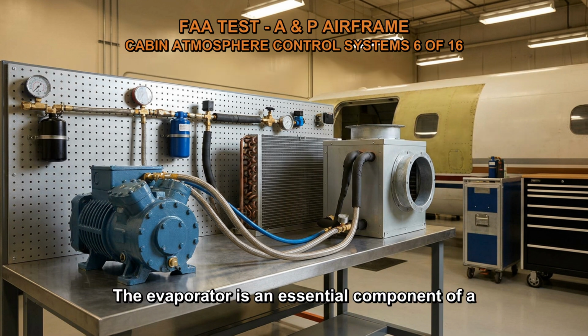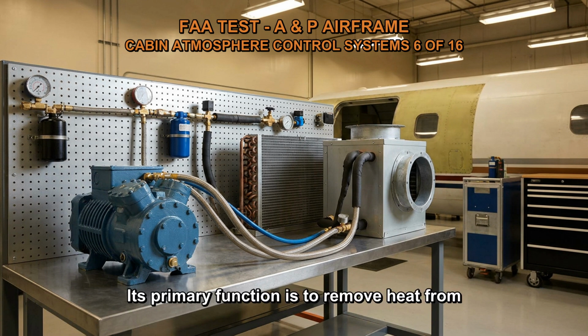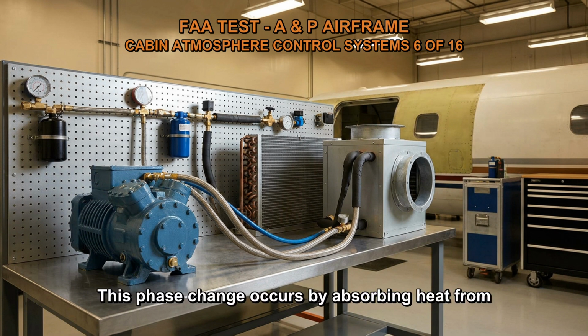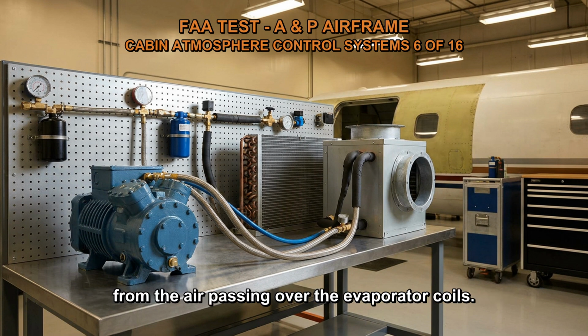The evaporator is an essential component of a Freon cooling system, specifically in the air conditioning system of an aircraft. Its primary function is to remove heat from the cabin air and lower its temperature. When the refrigerant, such as Freon, enters the evaporator, it undergoes a phase change from a liquid to a gas. This phase change occurs by absorbing heat from the surrounding air, including the cabin air. As the refrigerant evaporates, it extracts thermal energy from the air passing over the evaporator coils.